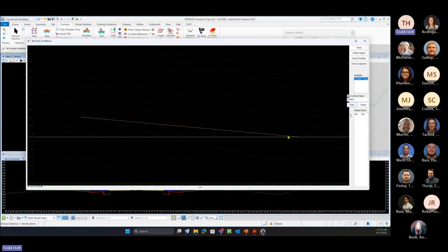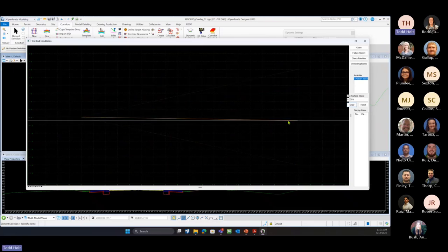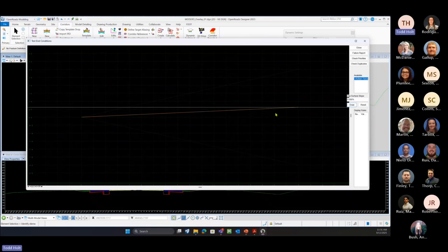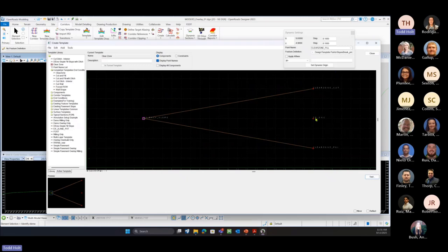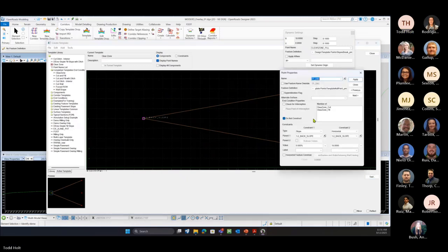So there we can have a variable slope that we can set to 18 feet or add a label into that if we need to control that a little bit more, right? So we have our default that is going to put it in there, but then we can come in and build off of this point. So if we wanted that horizontal, maybe this is a parametric constraint, or this label, this is our right-of-way seek that we put in there. And we can use that.